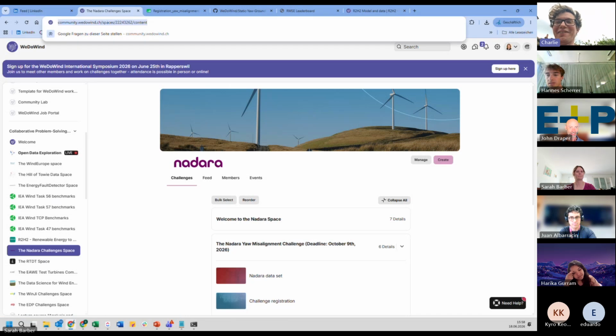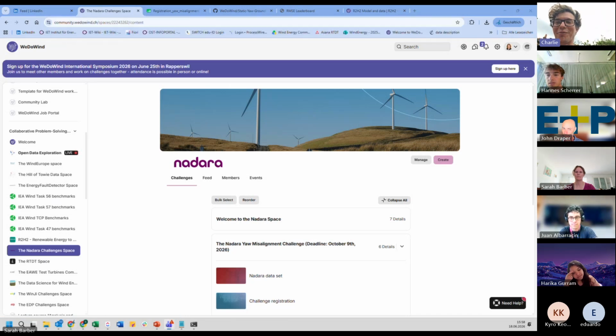I guess we haven't managed to solve the problem that we wanted to solve, which is around the static yaw misalignments and identifying them. But I think all of the analyses are really interesting and showing different issues or problems with determining something like static yaw misalignments. Even the bit around the sampling frequencies, it's very odd that you get hugely different results just based on whether you're sampling on 1 second, 30 seconds, 1 minute, 3 minutes, because that shouldn't really affect the end result.